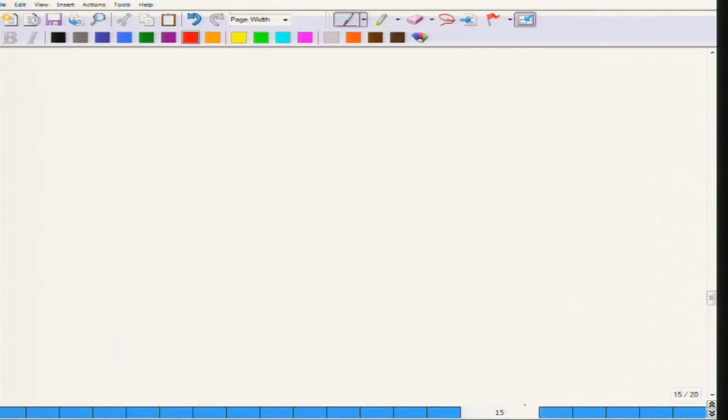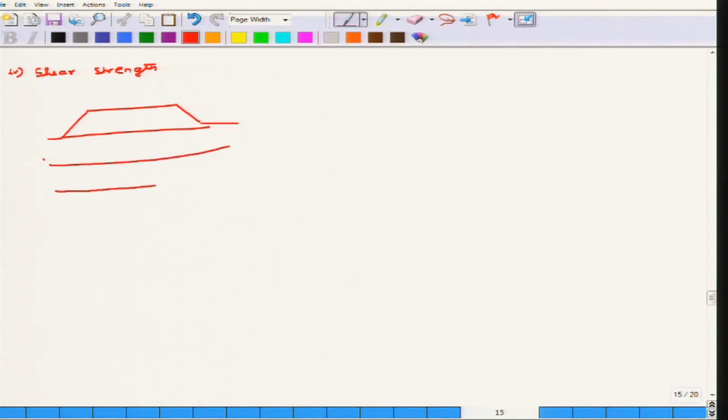Now, the next part is the shear strength and consolidation. These two parameters are going to tell you whether your soil is going to support the given load or not. From the point of view of shear strength, you have to assess what type of situation is there in the field. So, let us say that you are going to construct an embankment on that soil. This is the layer of sand. Now, the clay is virgin, or let us say that it has not been subjected to consolidation before, and this is the water table, and the embankment is to be constructed, or let us say an extra load of 700 kPa is to be imparted, within 2 months.